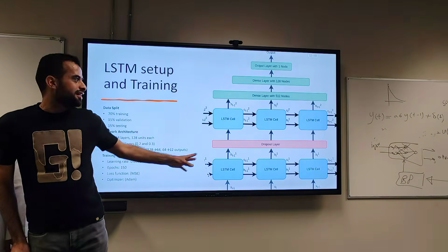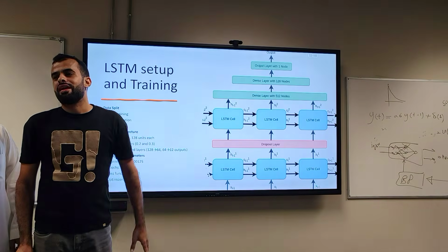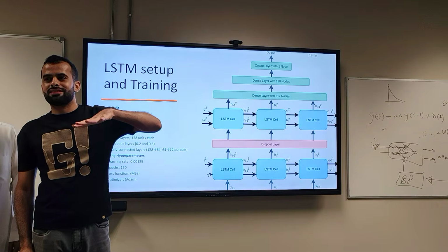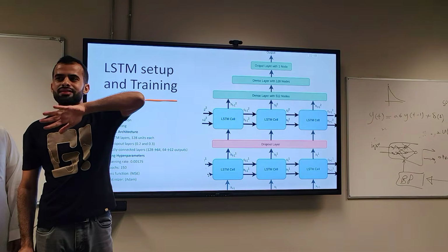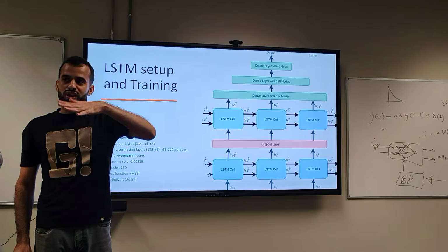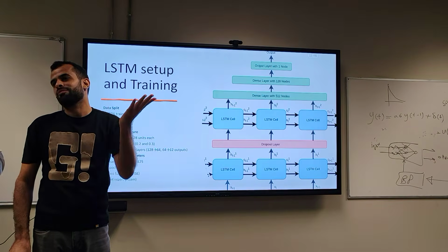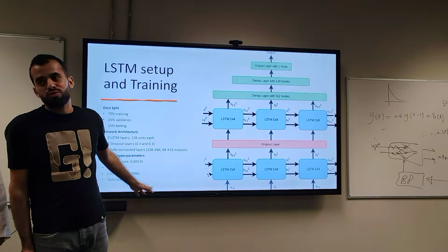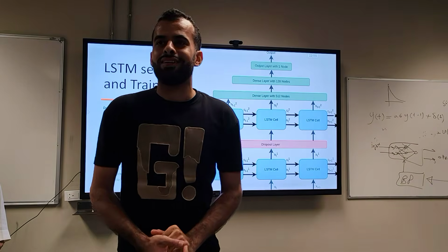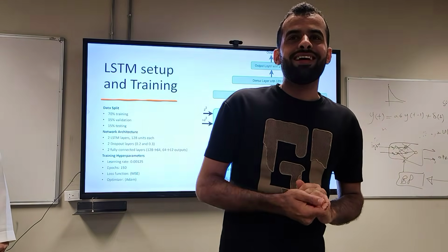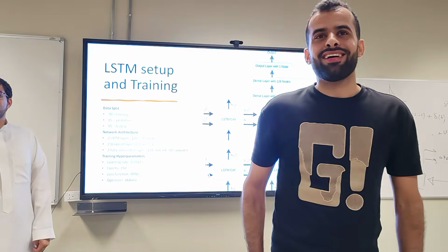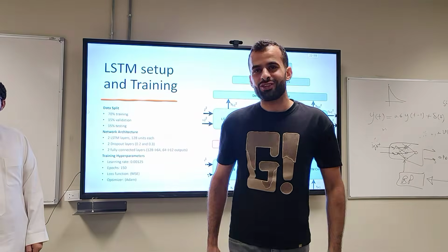I am thinking about using the geometric approach because the problem here is when you use the Euler angles, singularities happen at 90 or minus 90 degrees. So if we want the drone to flip and do higher maneuverability, we have to use the geometric approach on SE3 on the manifold. You don't have to use it. You can still do it without geometry. Yes, we can. You can use quaternions. Yes, quaternions work well.